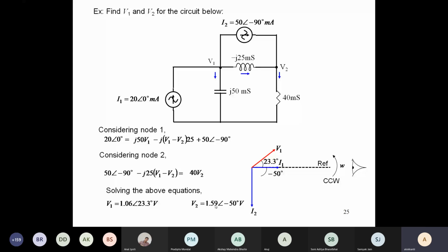Okay, so that is V1 and V2. It is not just the magnitude; you have to also show the angle where that phasor is, and similarly for V2. This is going to come again and again, because we are right now in AC, and in AC any physical quantity has to be represented in the form of a phasor, to some proper scale. The currents are one type of physical quantity. For currents you can use one scale, for voltages another scale, and draw it in the phasor diagram. So this problem we completed.